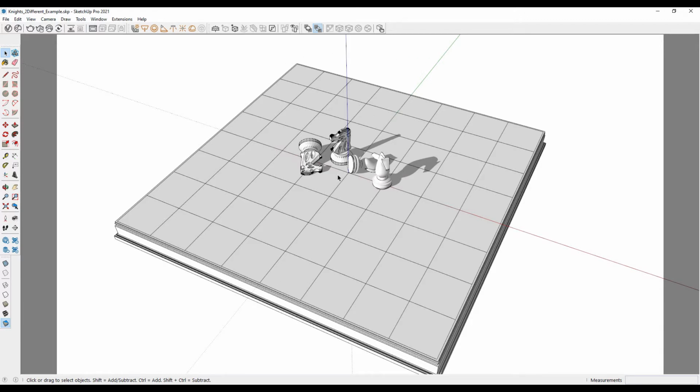So you might already guess I'm going to create a circle and place those cameras on the circumference of the circle so that they point towards the origin. But in this case, I'm going to use the circle tool, but instead of it having 24 sides, I'll type in, say, maybe 8S and hit enter. So I have an octagon, right? From the center, I'm going to tap the up arrow key, so the octagon is always going to be facing up.